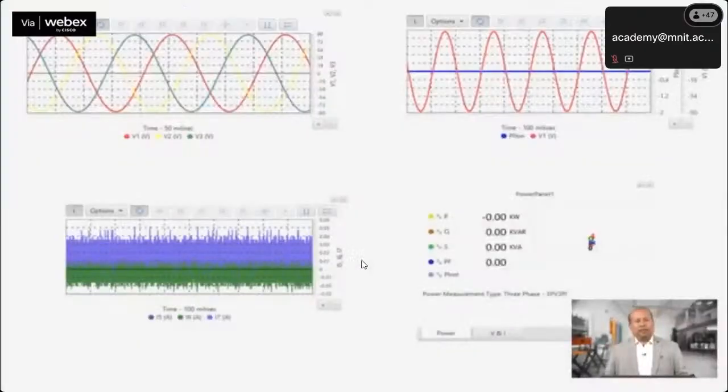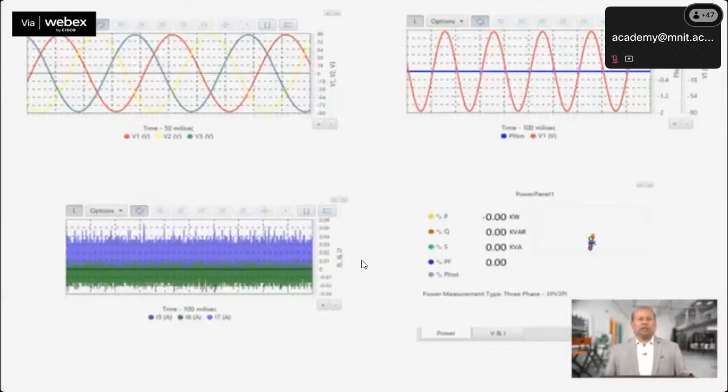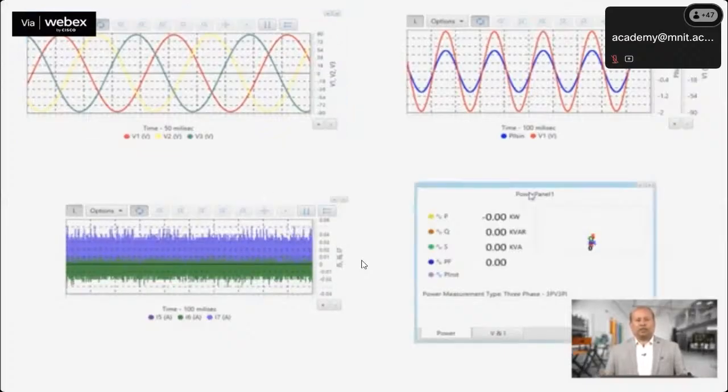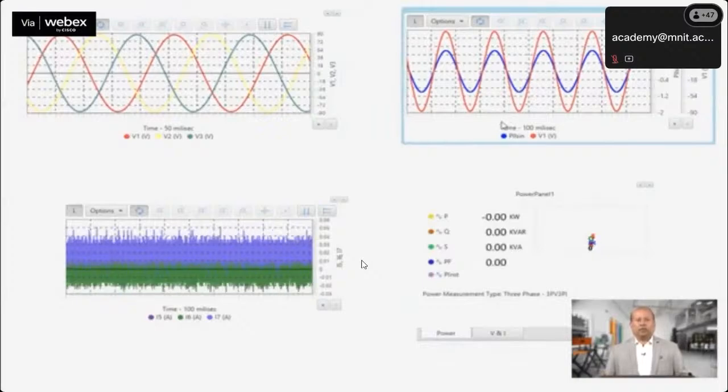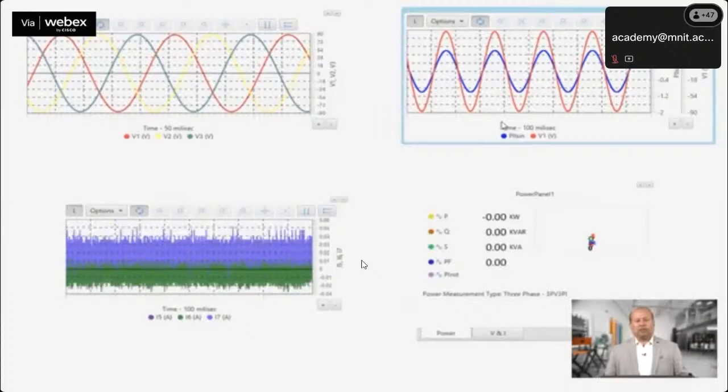In the beginning, we will synchronize the BESS converter with one of the nodes of the IIT Roorkee network. After activating the PLL to achieve grid synchronization, we can observe in the right top waveform that the grid has been synchronized with the BESS converter.